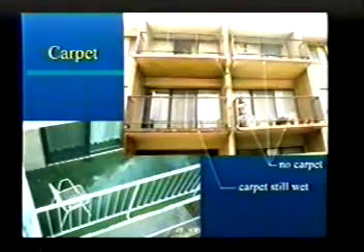Now with the lab analysis, I could also tell how deep that goes. If I put a simple repair material on top of that, as Alex had said earlier, you have to treat your whole structure. If I put a repair material on top of that, that repair material is going to come apart. Why? Not because the repair material is bad, but because that concrete right there is bad, and that's going to come apart. So you have to know your source. If you know what the source of that problem is, you can probably fix that.